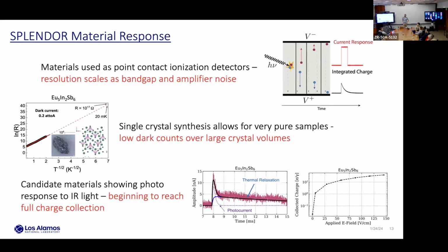Just for clarity, this is all cryogenic, right? It's not room temperature. Yes. Sorry, I'm so used to working at cryogenic levels, I assume everything is. A lot of the data we've taken is at 4 Kelvin, but the experiment itself operates at 10 millikelvin. That's a downside for the general purpose of these: with a band gap of 10 millielectron volts, you need to be at cryogenic temperatures because it's basically a conductor at room temperature.